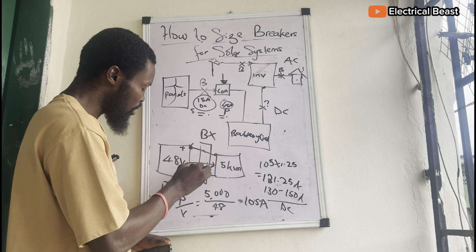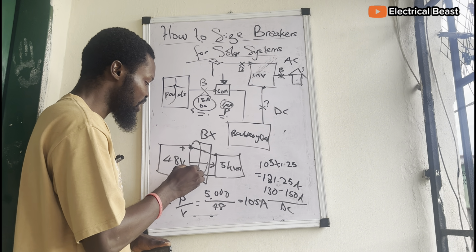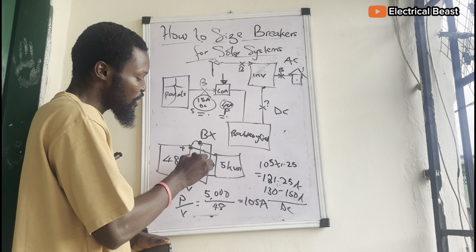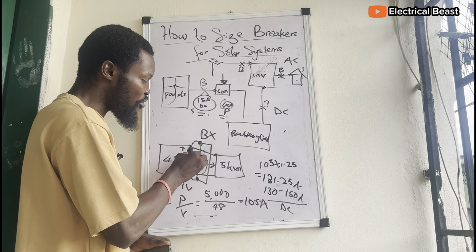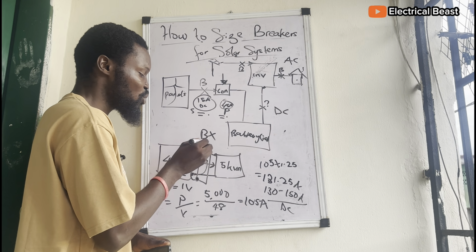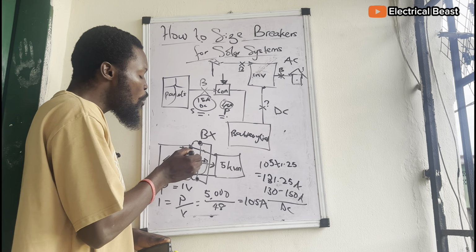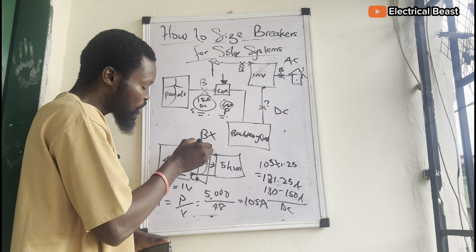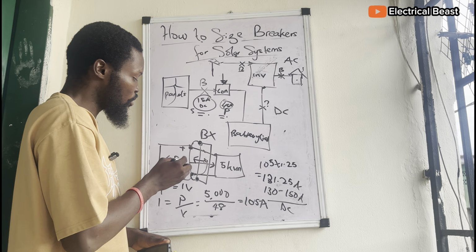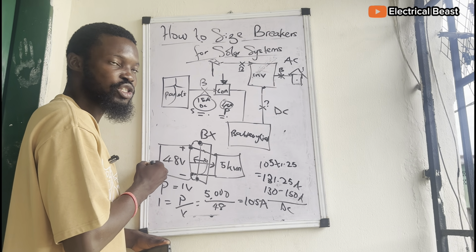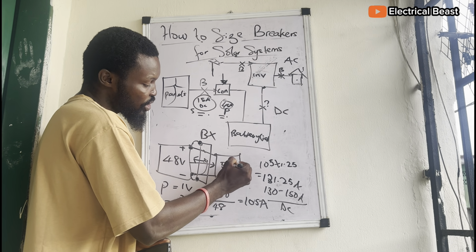When you add the breaker, the short circuit current goes through the breaker first. And when the breaker is properly sized, it's going to trip off or it's going to damage the breaker. It will not get to the inverter. So there'll be an open circuit on this breaker side. It will prevent that large amount of current due to the short circuit from going straight to the inverter.